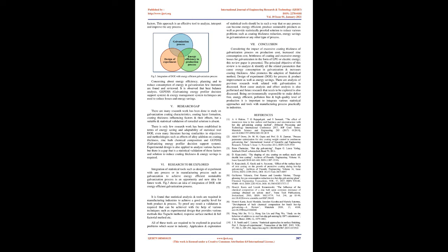Mostly hot dip batch galvanization is done manually. Lack of training, coordination, and less skilled workers affects galvanization. This is because maintaining a standard working temperature with a required immersion time is difficult manually, as well as lack of knowledge about how a minute delay in immersion time and improper temperature affects coating thickness.